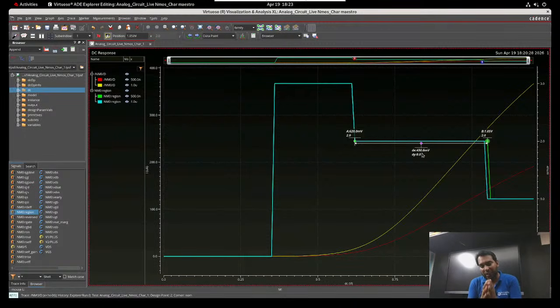We will discuss all these, the differential pair, current mirror, common source amplifier or any amplifier, on the basis of ID versus VGS and ID versus VDS only. If you are good in ID versus VGS, ID versus VDS, and you are good in understanding of that value, you can very easily design to meet your specification.